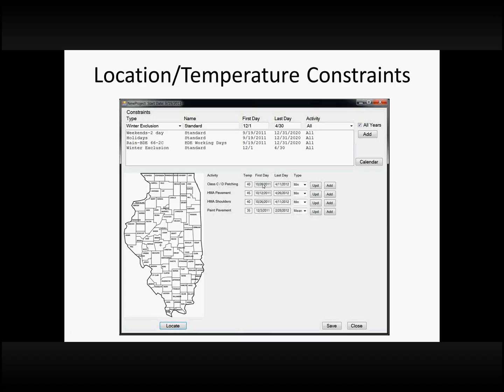So it doesn't say that we know that there may be days earlier than that it's going to be too cold. There's also going to be days later than that it'll be warm enough. So this is kind of the average and what we'd expect to be the days we wouldn't be able to do certain activities based on the temperature requirements for performing that. This is where I said we could base this on the minimum daily temperature, the average daily temperature, or even the maximum temperature. So it's depending on the judgment of the scheduler.